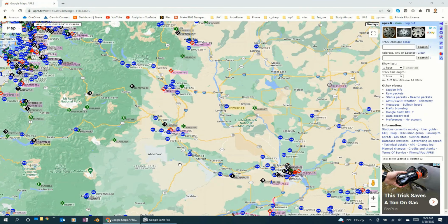Alright, so as we saw, we were able to track and hear our APRS packets locally at our local ground station and decode those via Direwolf and plot them via PinPoint APRS. But again, during the actual mission, we didn't connect to the iGate, so we weren't forwarding our APRS packets to the internet for other people to see. Now, even though we weren't doing the forwarding, other people and other iGates and other stations in the area were able to hear our packets and forward them to the internet, for example to APRS.fi. So several people in our party were actually able to track the balloon via APRS.fi.